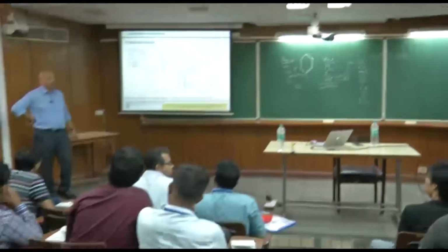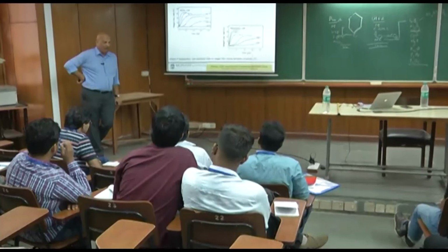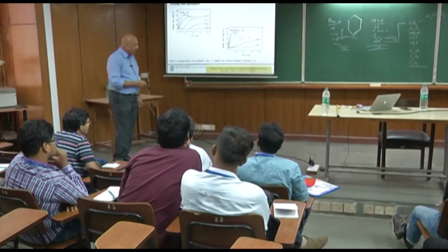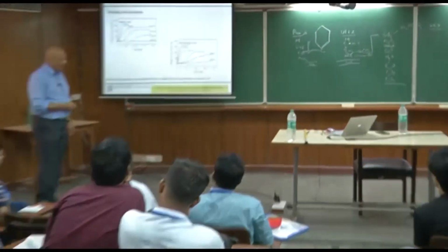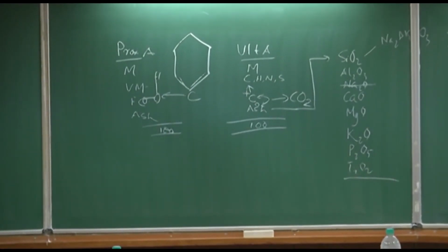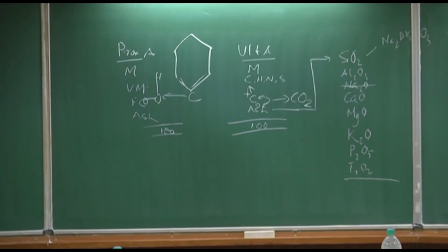Volatiles are the gases of carbon, hydrogen, nitrogen, sulfur, etc. They never come out as elemental oxygen, never. It will come out as CO2 predominantly, to some extent CO, and to some extent NO as well, and then that NO can become NO2 later.